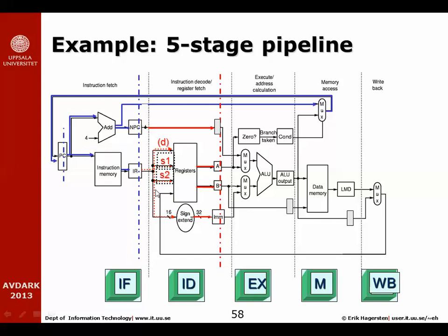So we take those 16 bits and we have to sign extend them, and we have to make them look like a full-fledged 32-bit value before we latch them here, because we want this value to come out here to look just like the values that came out of the 2 registers, and they are sign extended 32-bit values stored in each one of those registers. So here we have 3 sign extended 32-bit values.